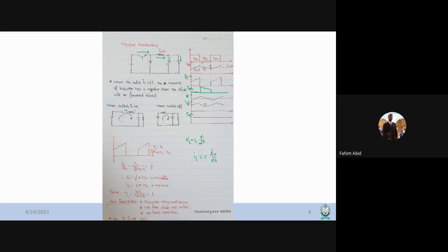This can also be seen, as I said, from the impedance or the reactance of the capacitor, which is basically X of C, which is inversely proportional to omega C. So as the C value is going high and high, your impedance is basically going down. So whether you increase the frequency or you increase the size of the capacitor, you will basically reduce this ripple content in the output DC. You will see it in the upcoming slides.